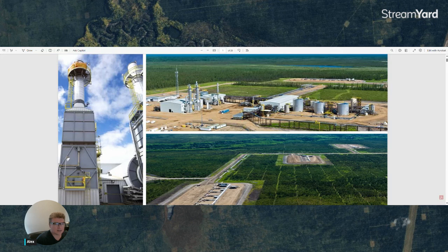We talked about basically extracting data from AccuMap on the asset perspective, then extracting data from individual pads, understanding parameters like steam injection rates or production rates, steam to air ratios, instantaneous and cumulative, gas injection rate, which is basically the NCG, and really plot the relative performance from SAGD to NCG. And so one of you is working on this project, so this is in benefit of everyone.